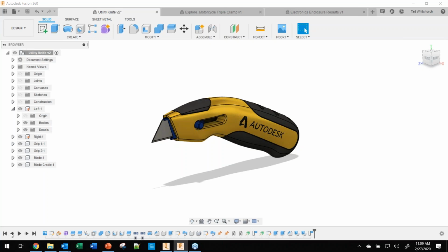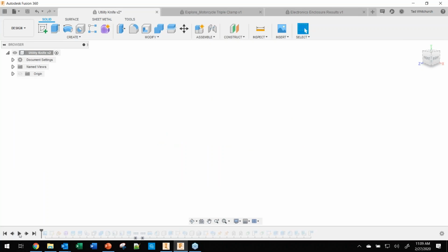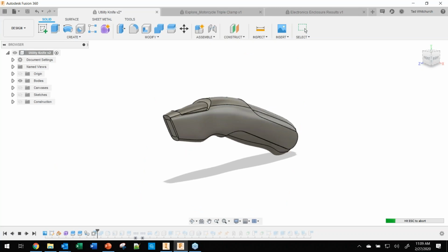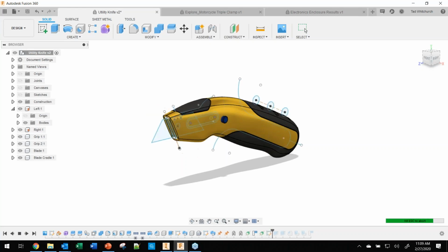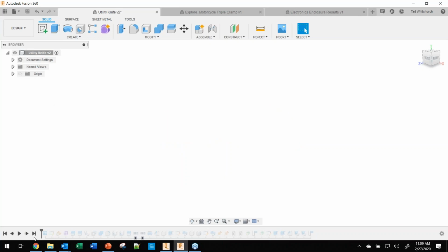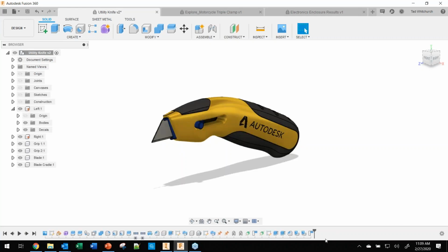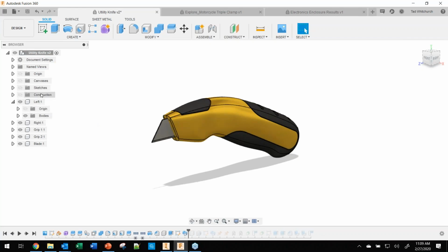And just like in Inventor, you can rewind this, hit play, and go through how this part was put together. So yes, within Fusion, it does maintain the history of the design as built, and you can, of course, edit any of those features at any time, just like you would expect, and very familiar, similar to Inventor. We can roll back to certain areas within the design by simply dragging that back.